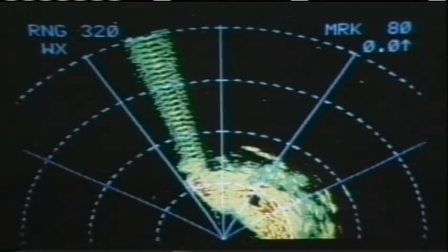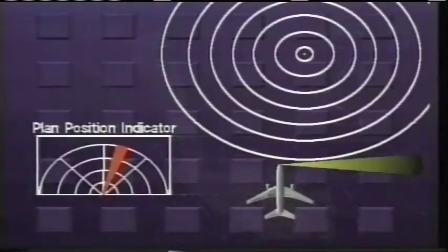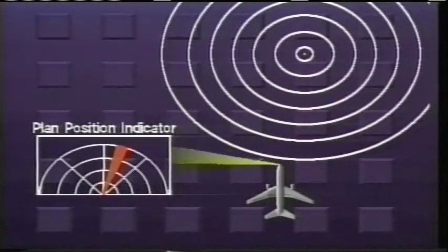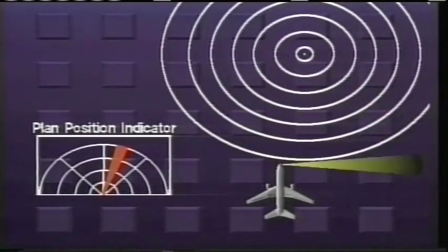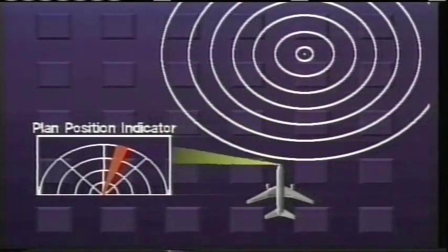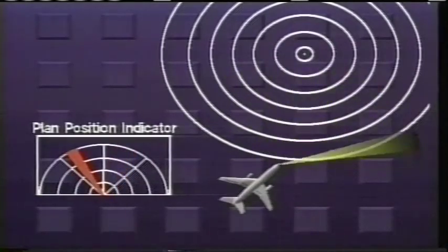The main cause of spokes is usually interference from powerful military ground radar. This does not indicate a radar system failure. If you are uncertain whether the radar system is malfunctioning or if the spoke is being caused by an external source, change the heading of the aircraft slightly and notice if the heading of the spoke changes in the opposite direction the same number of degrees. If it does, it is external interference. Ignore it.